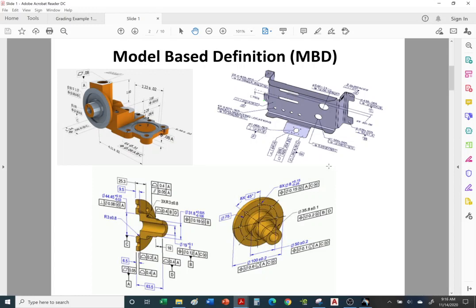And when it comes to finding dimensions for parts that are not labeled, so for example, let's take a look at this tab. They didn't label this with a dimension as far as how long this tab is. So to find out what this dimension is, you actually open up the 3D model in CATIA and use your calipers to find this length. So let's say this length off the model is exactly 1 inch.